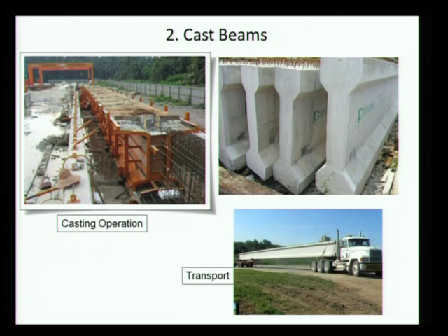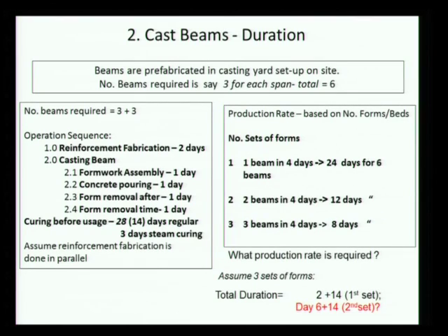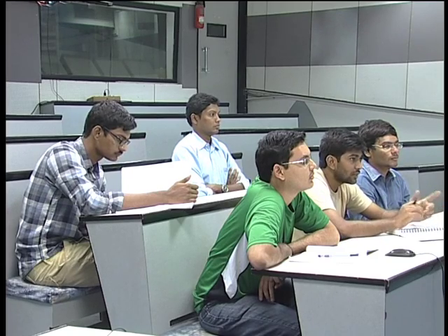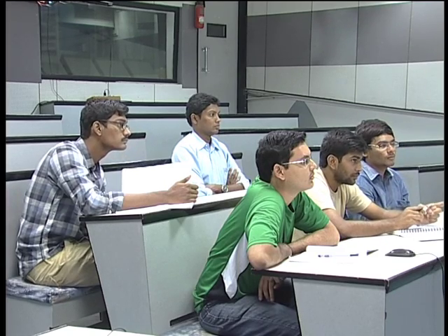It varies. It depends on what kind of lifting you can do, how far you have to move it, and various other issues. Yeah, you had a question? In the first set, 2 plus 14, even if the bed is free because the reinforcement is being fabricated somewhere else, we still need 4 days. That's right, you need the days to fabricate the reinforcement. Absolutely right. But in the second set, you don't need it because it is over.